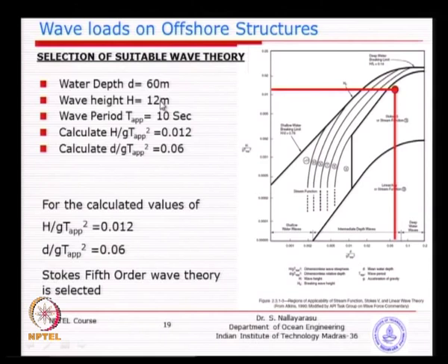It will not be possible to propagate, because by the time it reaches 15 meters itself, it would have already broken, because enough water depth is not available. But at that 10 meter location, you may be able to get a 2 meter wave height. So, 10 meters versus 2 meters, you may still fall in either Stokes or Airy's wave theory, we do not know. So, it is all relative, rather than 60 meters being called deep water and 10 meters shallow water. There is no such thing. Every time you have to see the relative effect of water depth, wave height and the wavelength or wave period.